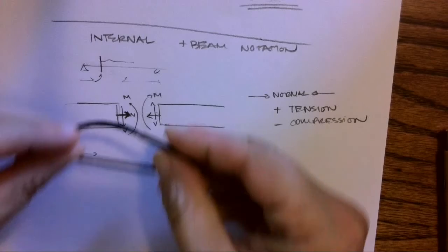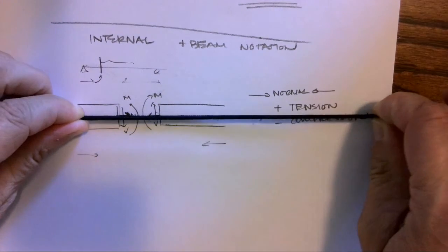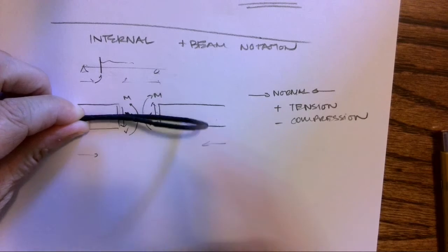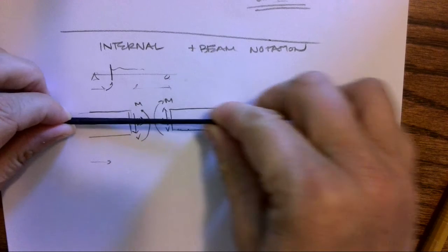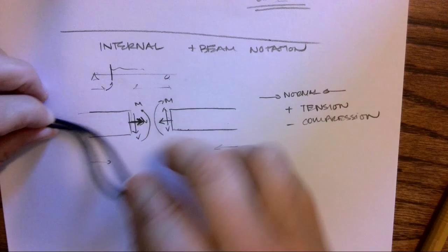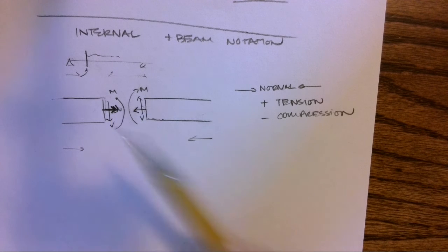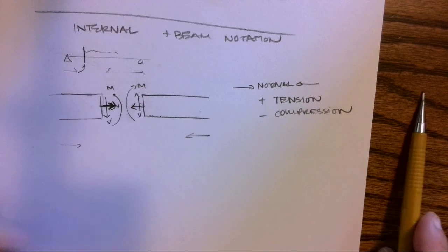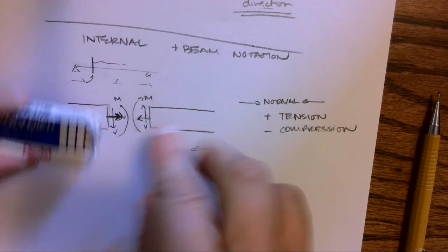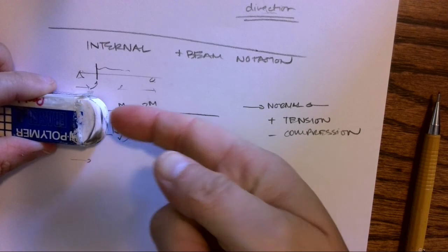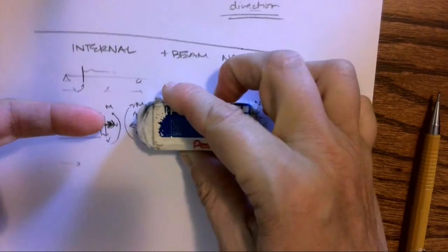So if I have a beam and I have an X load on it and I'm pulling it, when I cut that beam and look at the inside, I'm going to assume tension. If I indeed get that I'm in tension, I get a positive value, I'm going to call that like 20 kips, and it's positive. If I have compression and I'm pushing internally, so now I'm pushing this way towards the left, we can see on this side for compression, we're pushing towards the right.